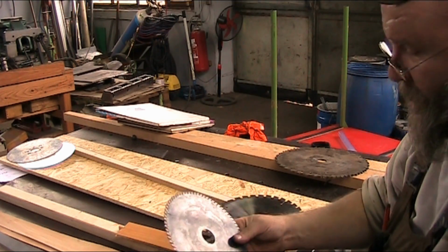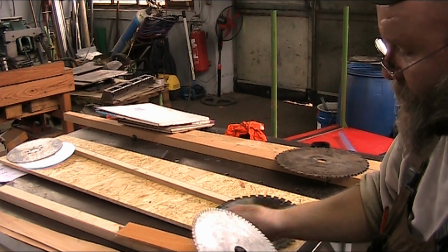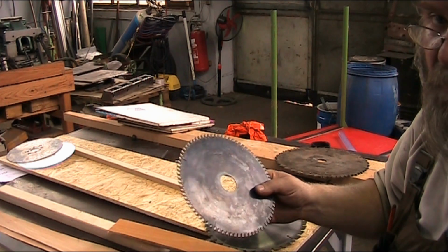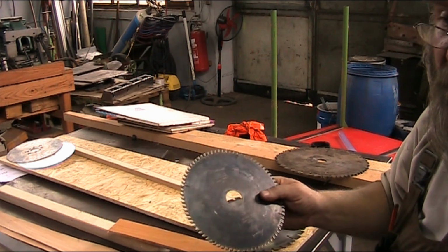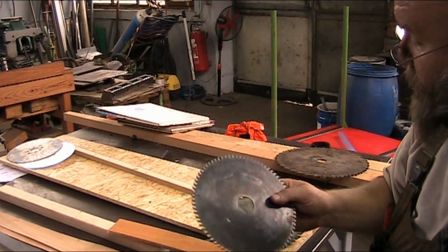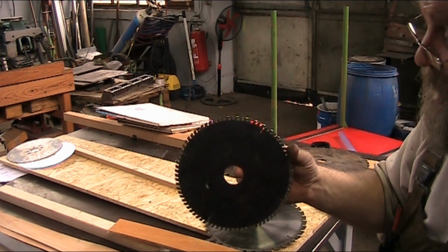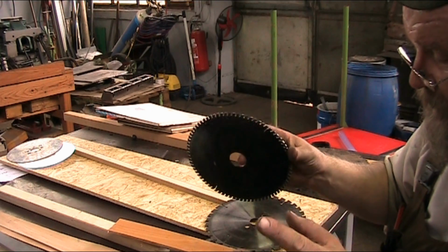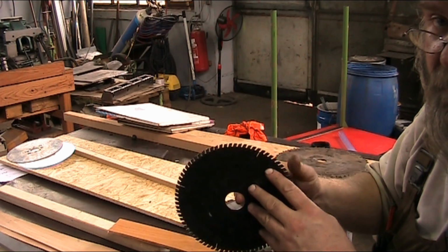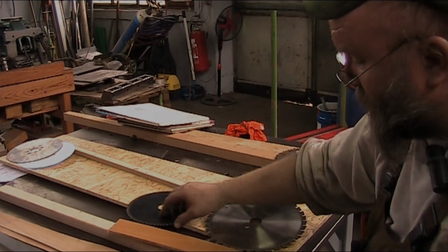Okay, this is a blade that you can use for not only this plywood, but this is also quite well suited for coated plywoods, coated OSB, and hard coated materials because of the tooth geometry here. The ridge of the tooth is going to be ground a little different in alternating patterns.